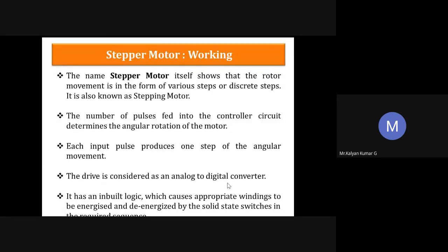With a low command pulse rate the motor moves in steps, but when the pulse rate is sufficiently high, because of inertia the rotor moves smoothly as in a normal DC motor. So you can summarize that motor speed is proportional to the rate of command pulses, and in that way you can control the speed of the motor.